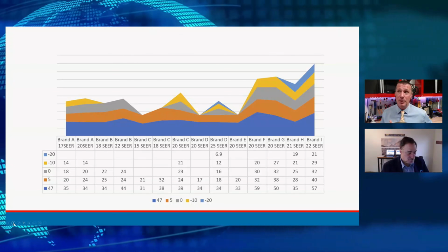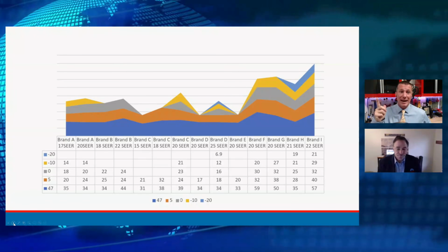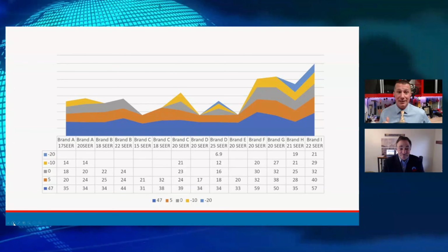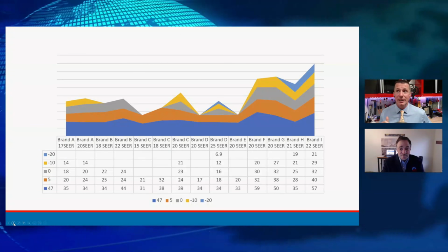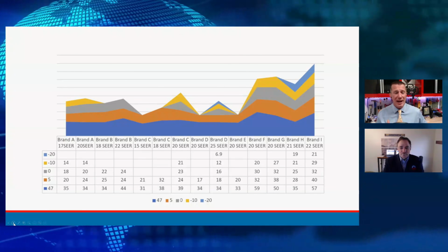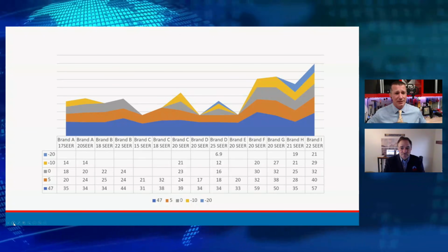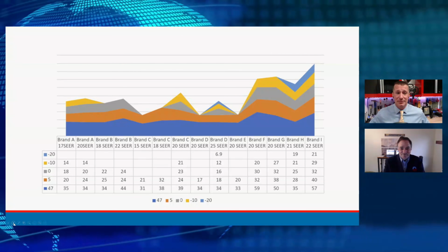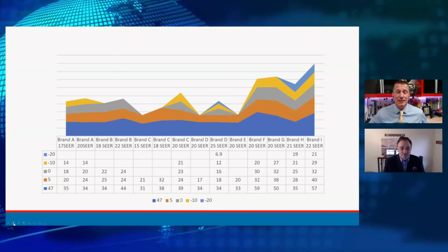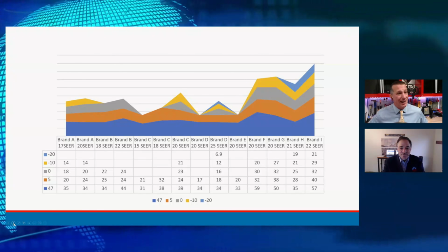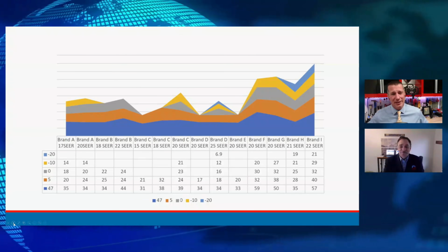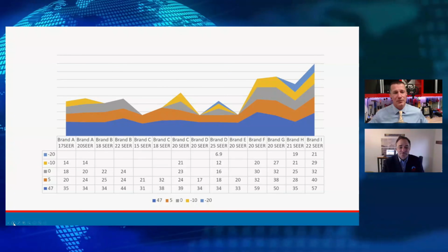And when we look at the heat capability of those, we look at that very last one, Howard. That is a 22 SEER piece of equipment on an air handler with ductwork, and it can produce 21,000 BTUs per hour at -20. I can't think of any place in the country where that wouldn't be a good fit. That's a significant amount of heat. Not any place I'd want to live. No, absolutely not. Most of the time, hopefully, we're going to be in that zero. Look at that. At zero, that thing's producing 32,000 BTUs.